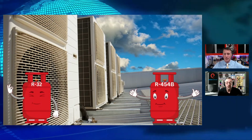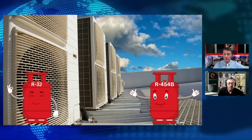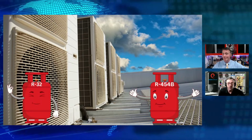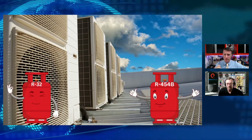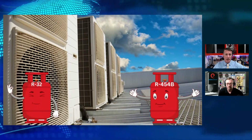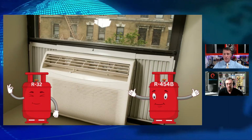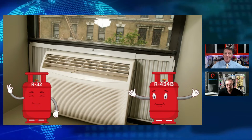Right, these two refrigerants for that application where we're 700 GWP or less. Some of the manufacturers are choosing R32 and some are choosing R454B. That's right. So as long as you learn best practices for low GWP refrigerants, you're covered for both of them, right? So that's the important part, is just to be prepared for whichever one. Now, what if we're talking about window units, PTAC units, right? Same scenario. We're going to be using the same refrigerants.